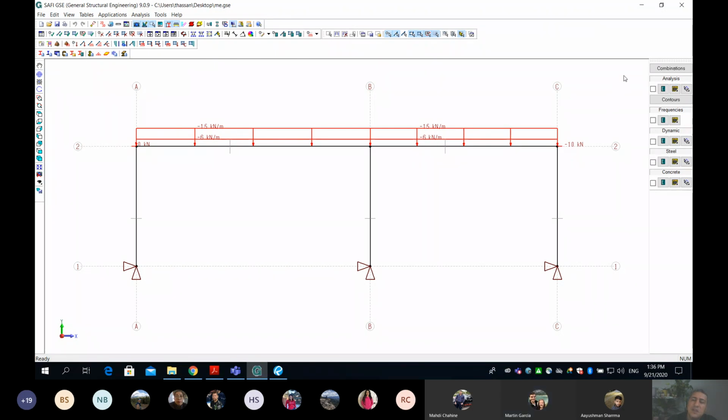Okay, so as I said, in order for you to start showing your results, we need that. It's a must. You must show your analysis results bar. If you have closed this one by mistake, then you go from the analysis menu, and then you go down to view/hide results bar, and it should be okay.